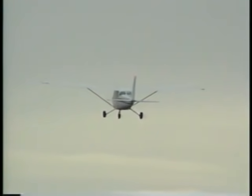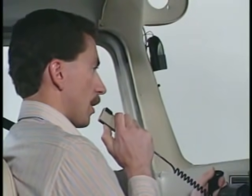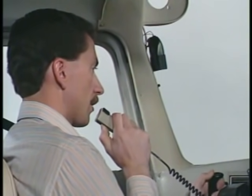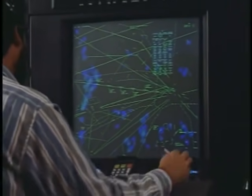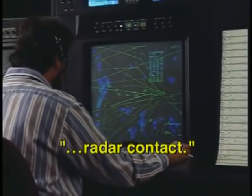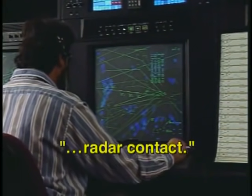After changing to the departure frequency, your initial call should include your ID, current altitude, and the altitude to which you're climbing. "Departure, Cessna 52241, 2,500, climbing to 5,000." By stating your current altitude, the controller can verify the accuracy of your Mode C transponder. "Cessna 241, roger, radar contact." Radar contact is used by the controller to let you know that your aircraft has been identified.